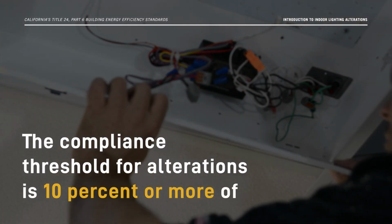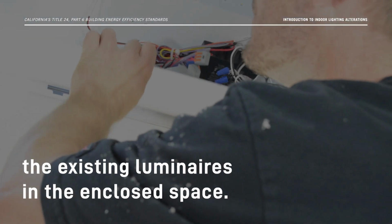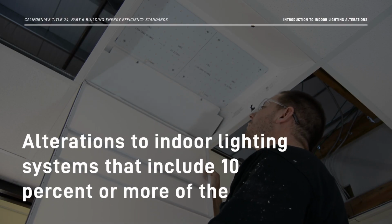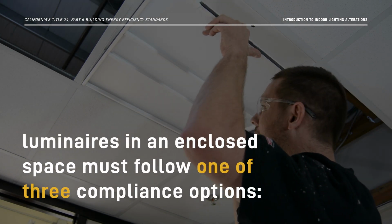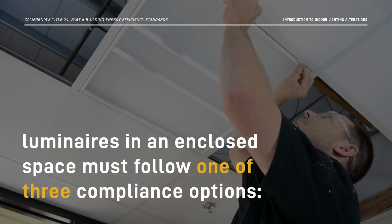The compliance threshold for alterations is 10% or more of the existing luminaires in the enclosed space. Alterations to indoor lighting systems that include 10% or more of the luminaires in an enclosed space must meet one of 3 compliance options.